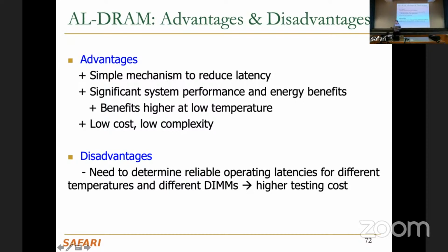So that's one. That takes time. If you want to parallelize this, you need to have testers, so testing devices. So you need to actually have many, many testing devices. And in real DRAM testing, these are actually very heavyweight testing devices that people use that can change the temperature, voltage, etc., with very precise ways. So that actually is costly also. So cost comes from time as well as these devices that you need to, let's say, purchase or devise so that you can actually do the testing in parallel as much as possible.